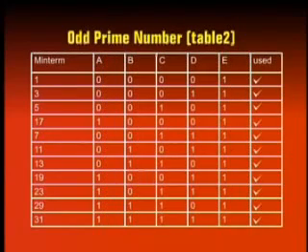The table of min terms is reorganized in terms of groups of min terms having 0, 1, 2, 3 and 4 ones. Thus min term 1 has a single one. The min terms 3, 5 and 17 have 2 ones each. The min terms 7, 11, 13 and 19 have 3 ones each. The min terms 23 and 29 have 4 ones, and min term 31 has 5 ones. This table is referred to as table 2.